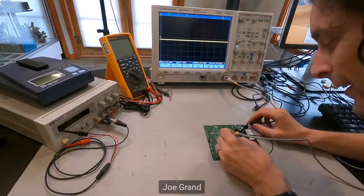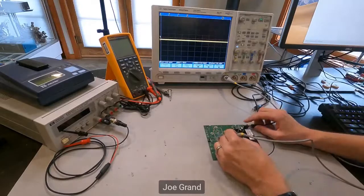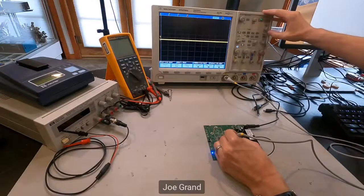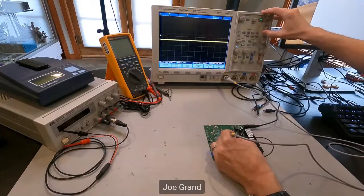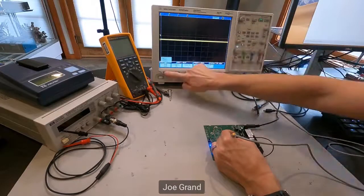I don't even know what line is what, but I can kind of see on the board the trace going from one chip to the other. So I'm just going to hold it onto pin 1. I'll plug this in and see, do we see anything? Oops. It would help if I was touching the thing. Okay, so we see something, but now I'm going to need to make some adjustments on my scope to actually capture those.